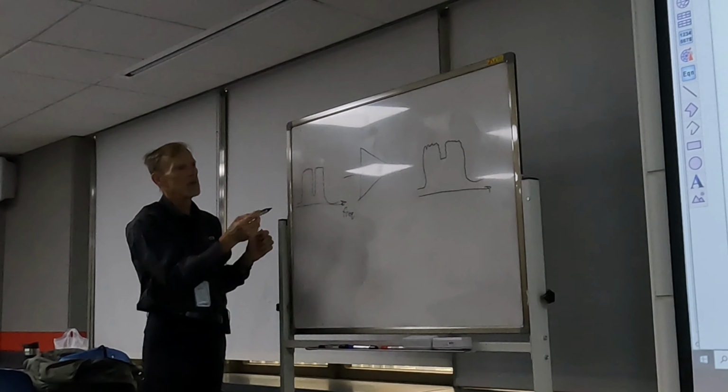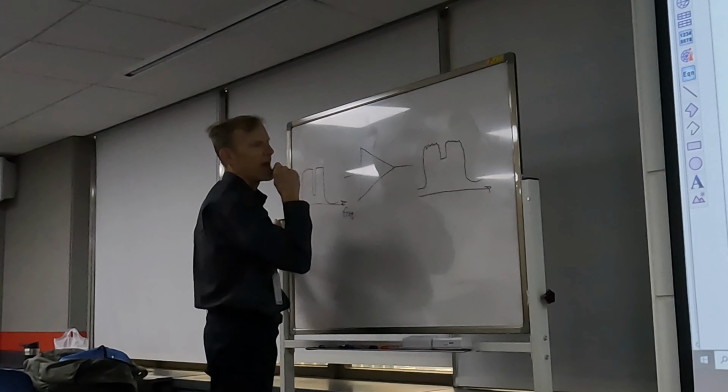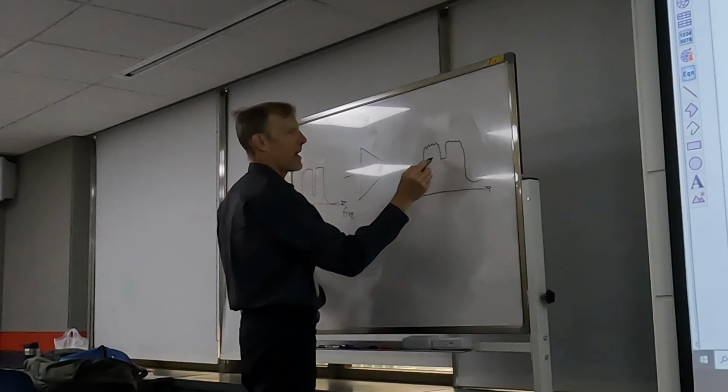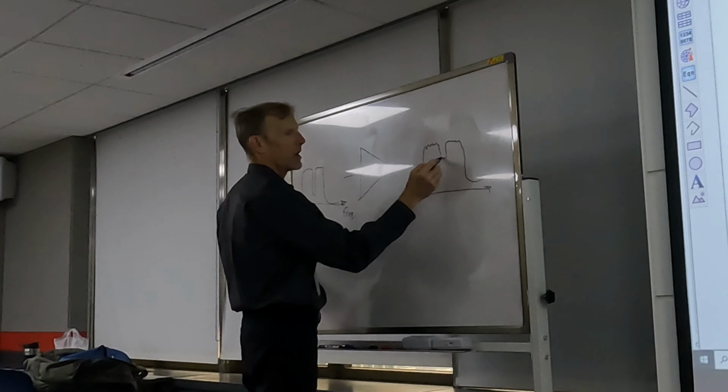So anyway, this is called noise power ratio, and it's a ratio of the power in the notch to the power in some band that's the same width but out of the notch. So you can do this. This is commonly done in, say, satellite systems, satellite communication test systems. But you can do this using an envelope simulation or using harmonic balance. There are two ways of doing it, and I can go over both of them.